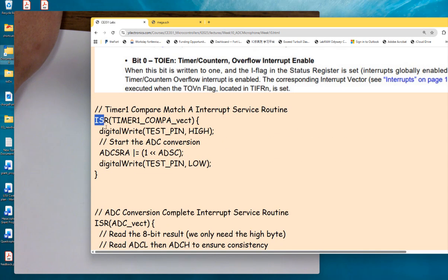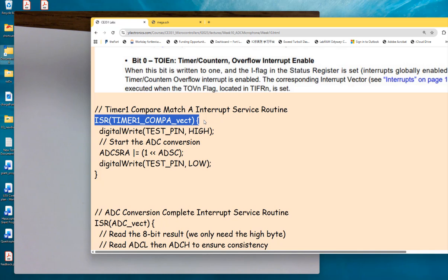That's the conversion ISR. It enters this ISR according to your sampling frequency, which you're doing here is 25 microseconds per sample. Could you calculate that really quickly for me? For 25 microseconds per sample, what's the sampling frequency? 4K, 40K, 400K? Which one? 40K. 40K.